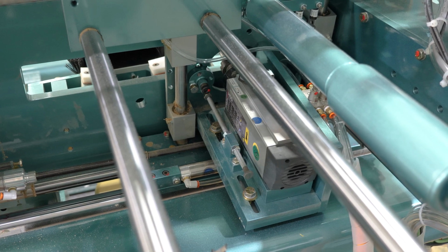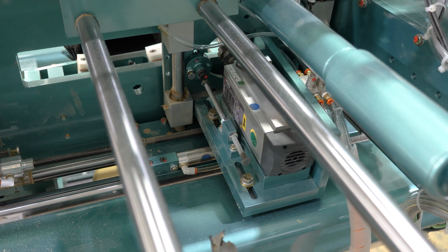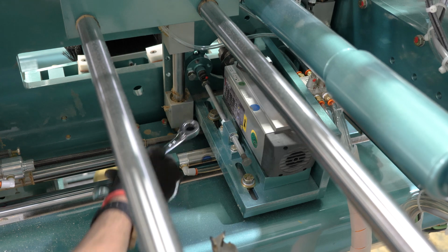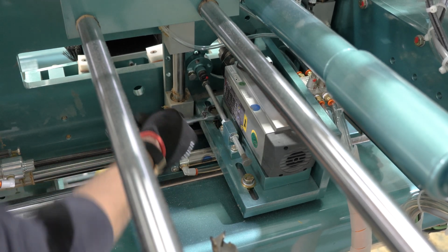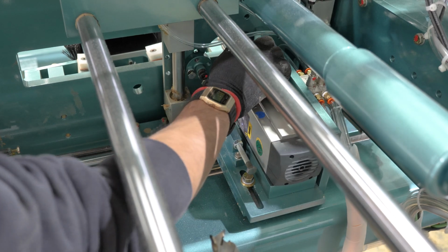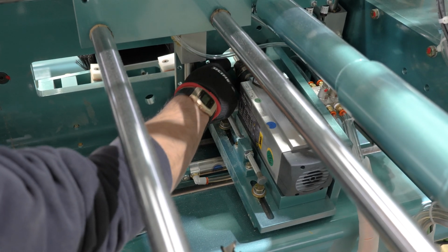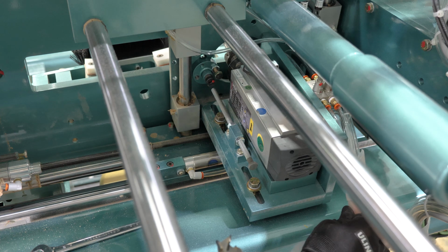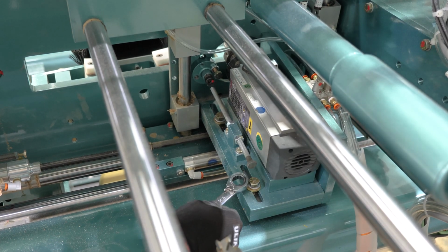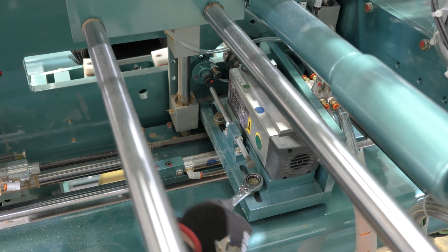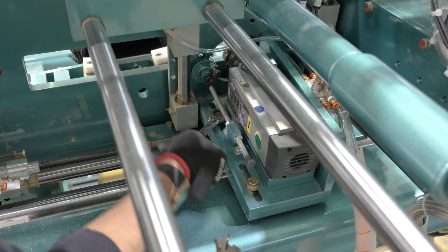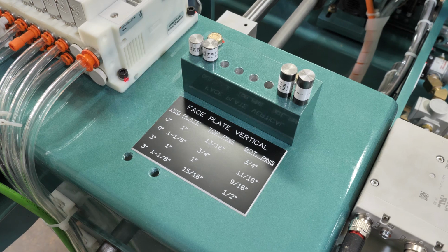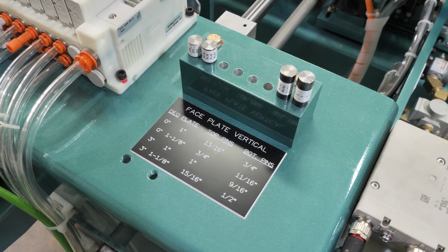When you're swapping the faceplate to 0 and 3 degree, you're going to want to make some mechanical changes. You're going to grab a 9/16 wrench and loosen up these two 3/8 bolts. And you're going to want to slide the router back and out of the way. You're going to go to your turret and swap over to your 3 degree depth and push it in. Then tighten up your router. Like so.